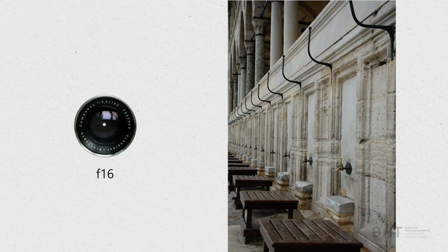Having a big depth of field is good in general because everything in object space that falls into it appears sharp in the photo. But note that the smaller the aperture, the longer the exposure time, and long exposure times carry the risk of blurring the images. You may be able to increase the ISO to solve this problem. If you are not recording raw data, you must pay attention to which white balance is set.